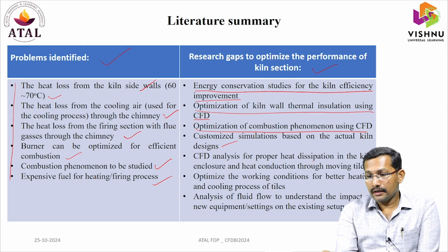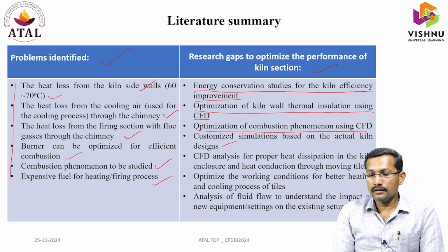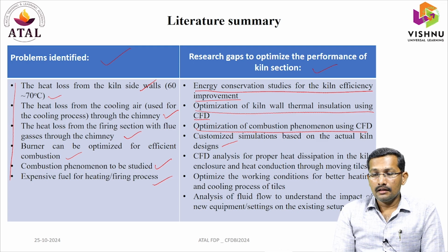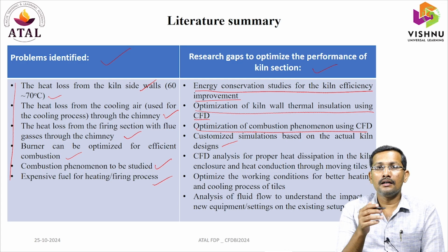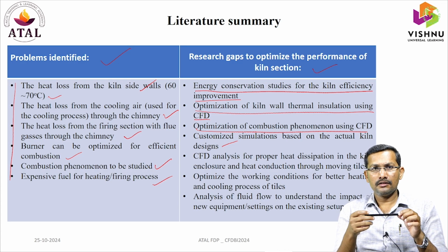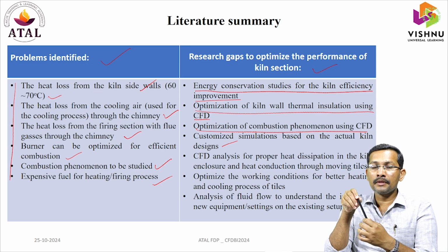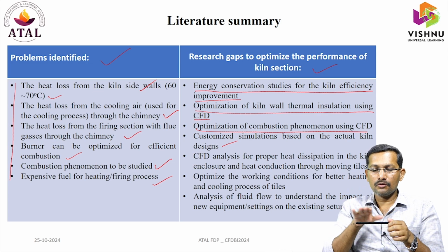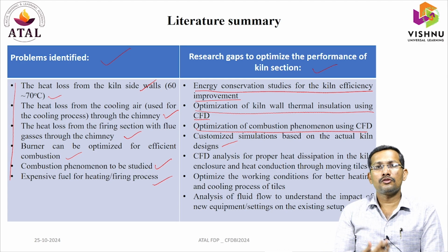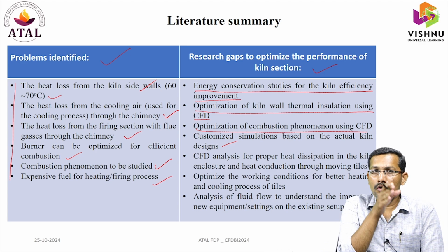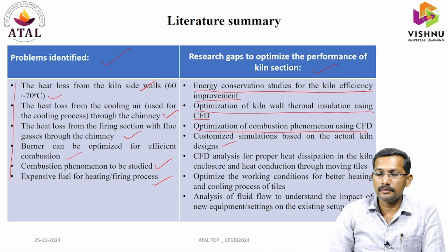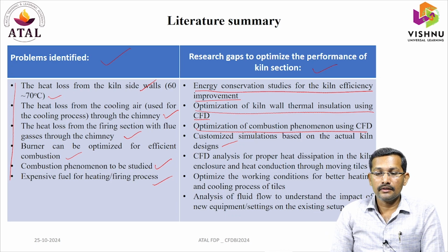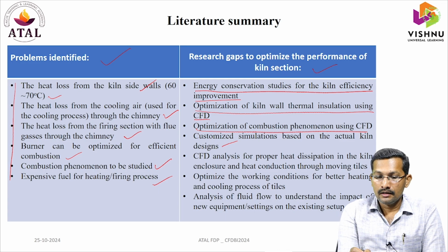CFD analysis for proper heat dissipation in the kiln enclosure and heat conduction through the moving tiles. Inside the kiln, there are rollers that rotate, and some tiles are on top of them. The tiles are also moving from module 1, 2, 3 and so on, getting heated up. They are also carrying some heat, which can be investigated and we can recover that heat.